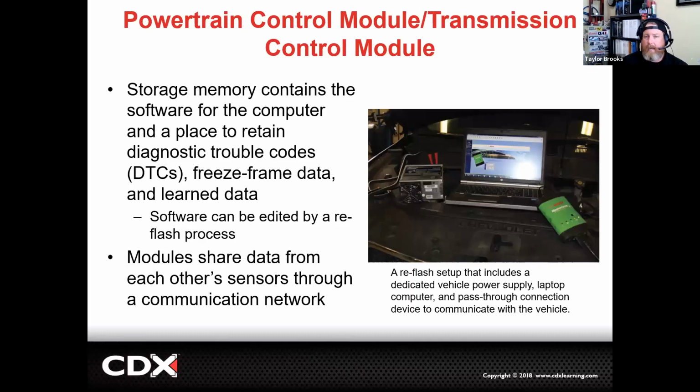The ability for us to have storage of diagnostics information and freeze frame data allows the mechanic to more accurately diagnose a vehicle. Why this is important with manual transmissions is quite often you can look at the transmission acting funny or the vehicle driving irregular and blame the transmission when ultimately it can actually fall down to something else. For instance, with drive-by-wire vehicles, it may be that the operator is trying to give the car more throttle, but it won't. Now, the transmission has the ability